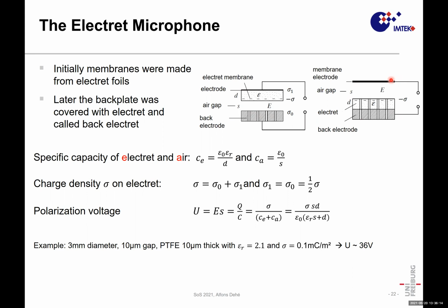You do this because optimizing the electrode functionality and the mechanical functionality at the same time is maybe not so easy. If you look then at the electrical situation in this device, we have a capacitance from this electrode. The electrode may have a dielectric constant of 2 or so, and we have a field in the gap between the electrode and the counter electrode.